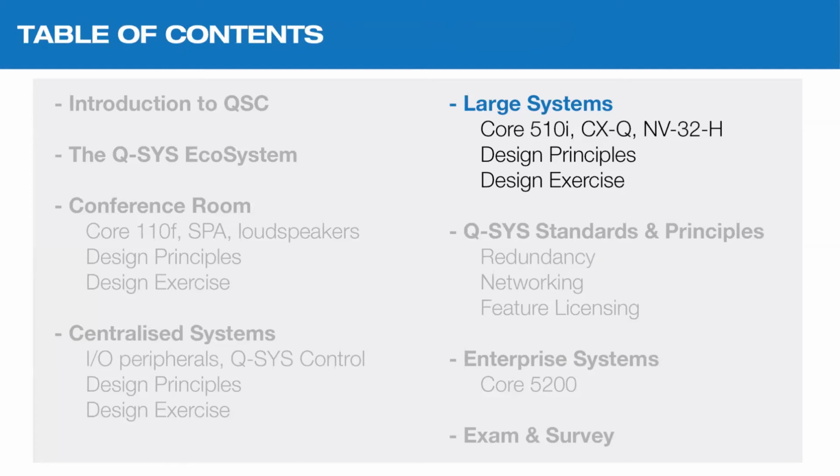And then Alan asks, can we use any PTZ brand camera or only Q-SYS? So we can control other PTZ cameras, but we can't use other PTZ cameras to do our IP bridging. So if you wanted to apply that system that MC showed, you would have to do this with the Q-SYS PTZ cameras. I know that's kind of expensive, but it's necessary because obviously we're outputting IP video, not baseband.